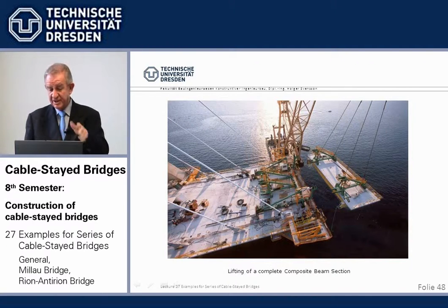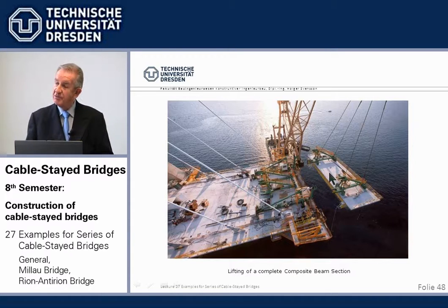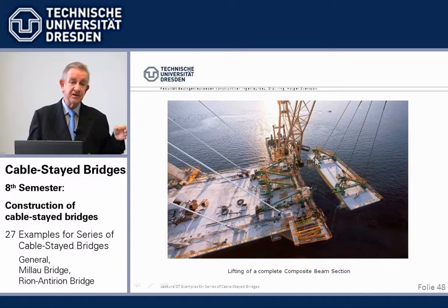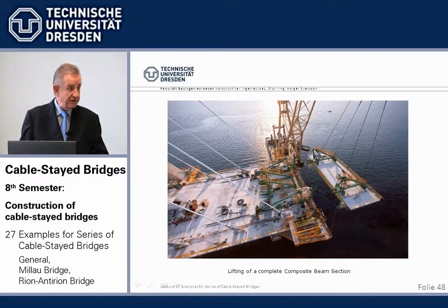Kap Shui Mun, but that's a little bit different, where we have the steel grid plus the concrete slab on top, lifted in. It helps a little bit with construction time, but of course I lose the big advantage of having to lift only, say, a 60-ton steel grid and the concrete in pieces, or this weighs about 270 tons.